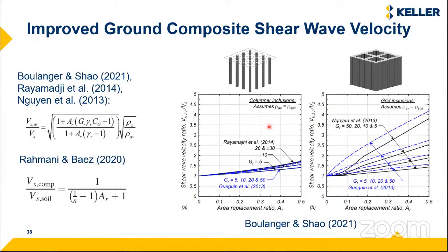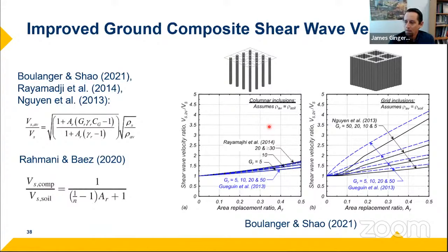Okay, we have a question: how to mitigate liquefaction potential below a large diameter structure like a water storage tank without disturbing the existing foundation? The kinds of things that you could look at are, number one, compaction grouting. If the layers are deep enough and there's enough overburden stress, you would prefer to take the tank out of service and core through the slab to do the injections. But it is possible also, we've done work before with horizontal directional drilling. You can come in from the side and do the compaction grouting from the side.